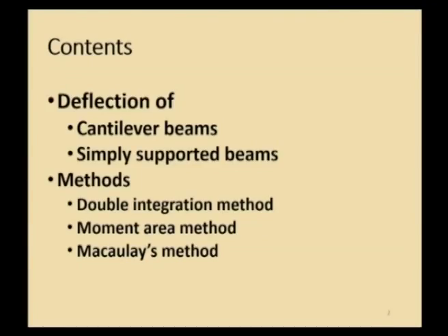In the double integration method, we will be integrating twice the bending equation and then we will be arriving at the deflection at required values or points. Also, we obtain the slope at required points.